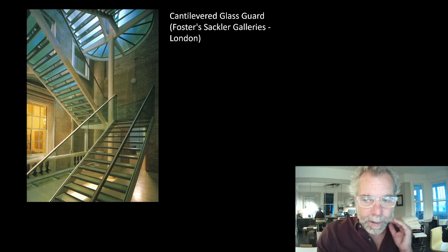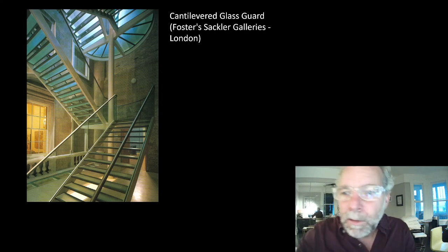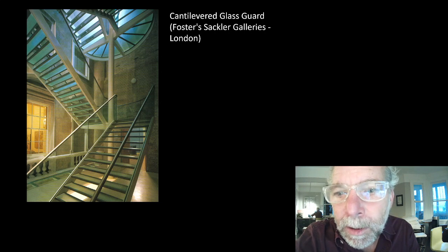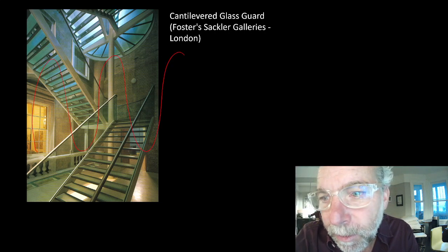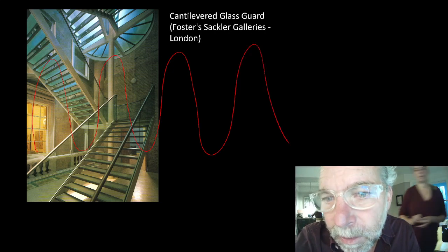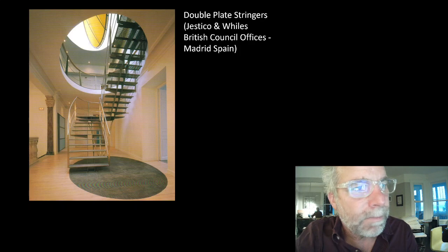Shannon talked quite a bit about damping. Damping is one of the things that influences our perception of vibration more than anything else, and yet it's the thing that we have the most trouble quantifying. So if we draw a vibration wave, it's a sine wave like this. There's our neutral position, the horizontal.